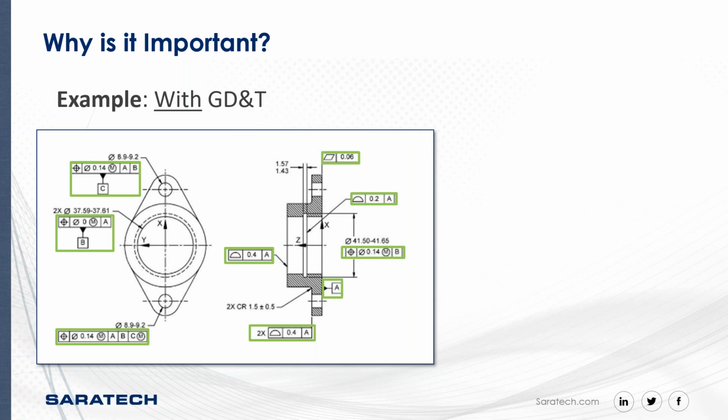So what the inspection person will do is basically reference B as the primary datum relative to where this hole is placed. So it has that bonus perpendicularity tolerance to datum A, or B, whatever this would be.